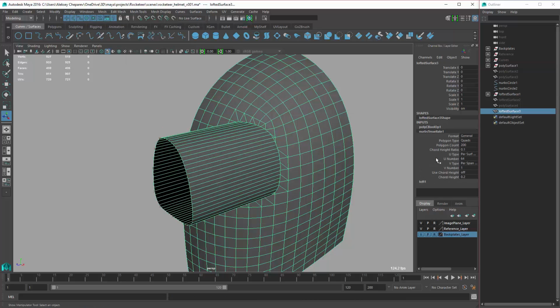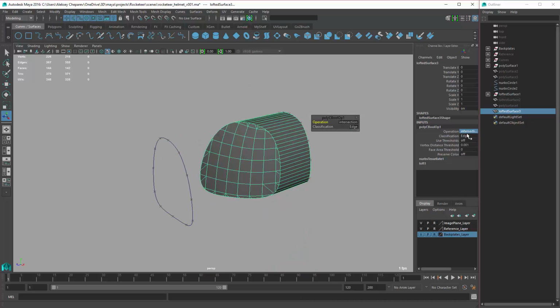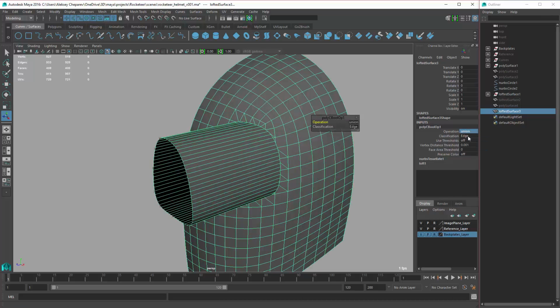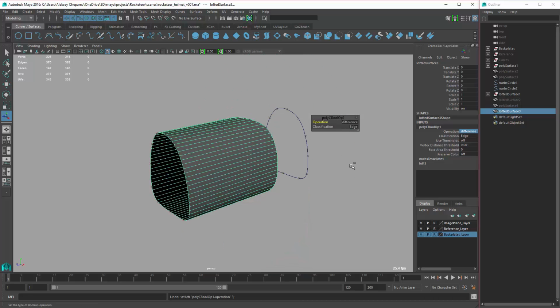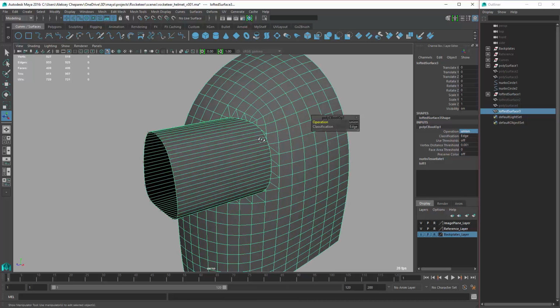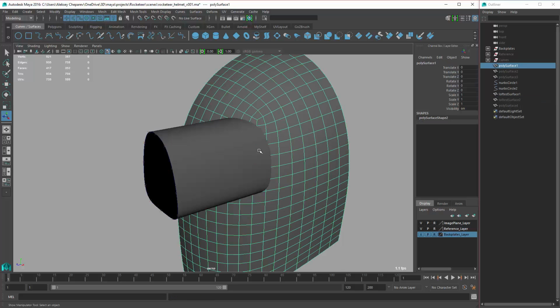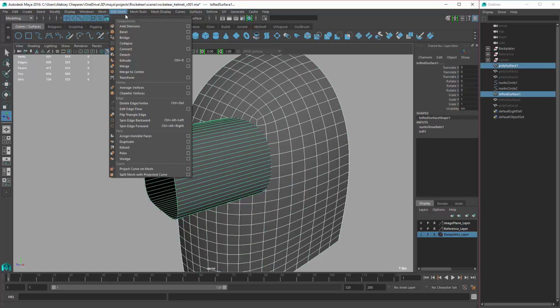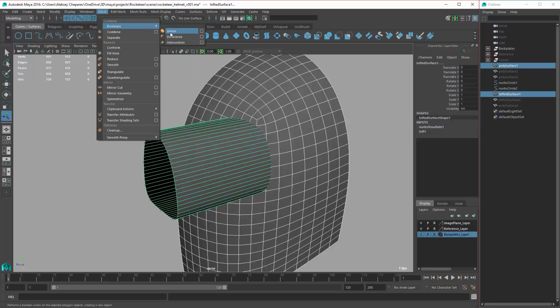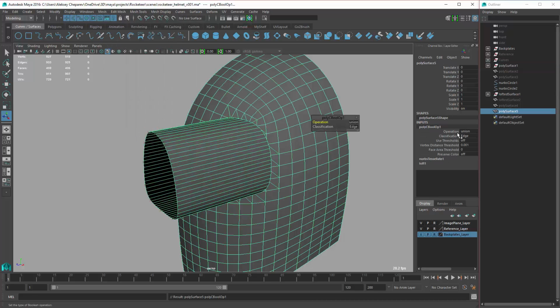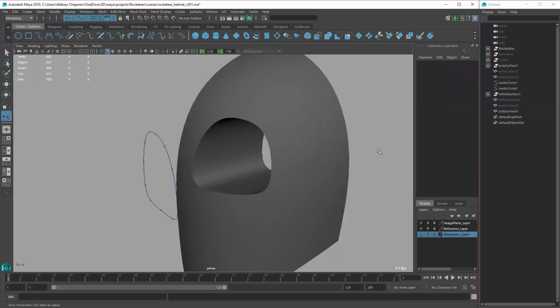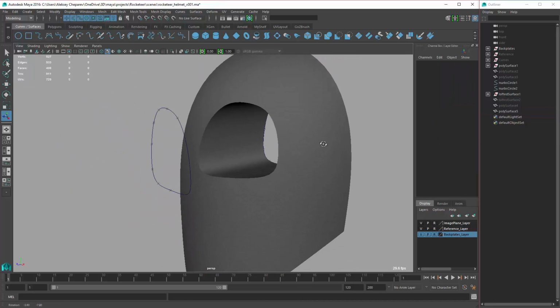Union, and then we can actually change to difference, intersect. Let's do union. All right, so let's change the order. Sometimes the order matters, so this is white, that's green. So if we change the order, I don't remember what it was, like that, and do the same operation, it will actually be different. There we go. I'm happy with this.